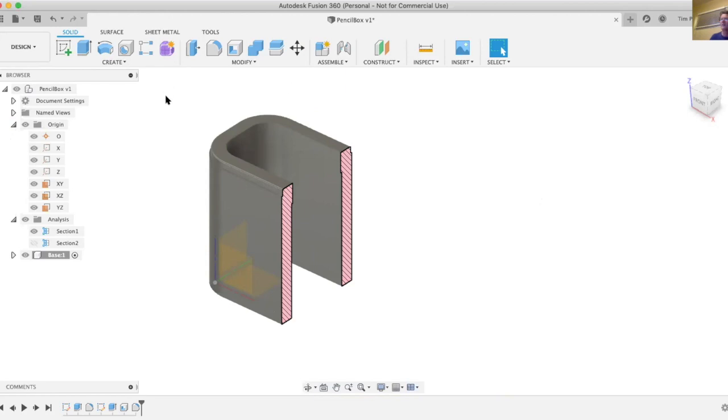And that makes life really easy. And then you can use those planes to mirror later features. So if you have a part with some complicated features that are mirror images on both sides of the part, you can define it all on one side and then just mirror it across. I think words kind of lose us without the picture. Yeah, I'll have to demonstrate that at some point.